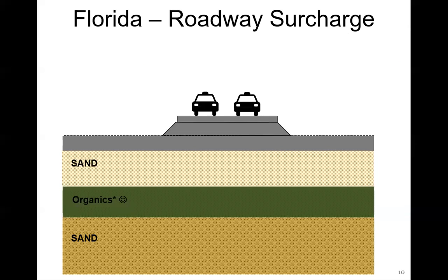It depends. That's one of the design things. So the function of permeability that we talked about, the rate at which water leaves, there's something very similar to that called the coefficient of consolidation, where they'll actually do these tests and determine how long it takes for soil to compress. So the time aspect of permeability. They would do that test, and then based off of the height and the other soil conditions, they could find an exact time.